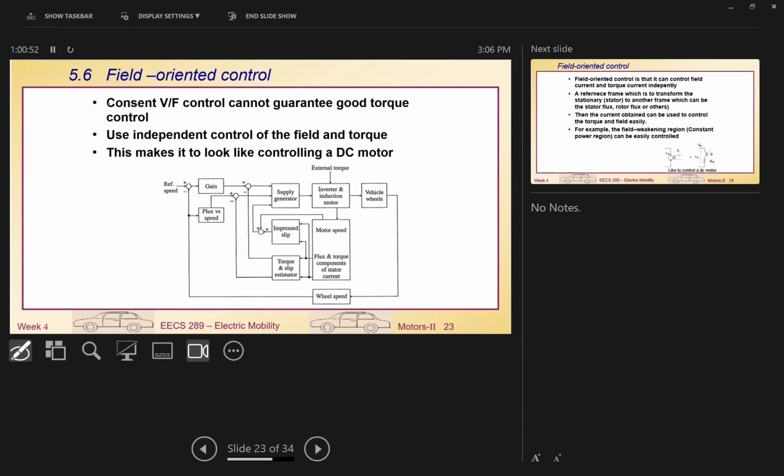They have no relation to each other. You can control them separately. That's quite nice, because in the past, with this motor, if you wanted to control voltage, you might affect your flux and your current. So we could not just use voltage control independently of the motor current or the motor flux. But now, using this control method with some algorithm, we can control them separately. So that's what happened.